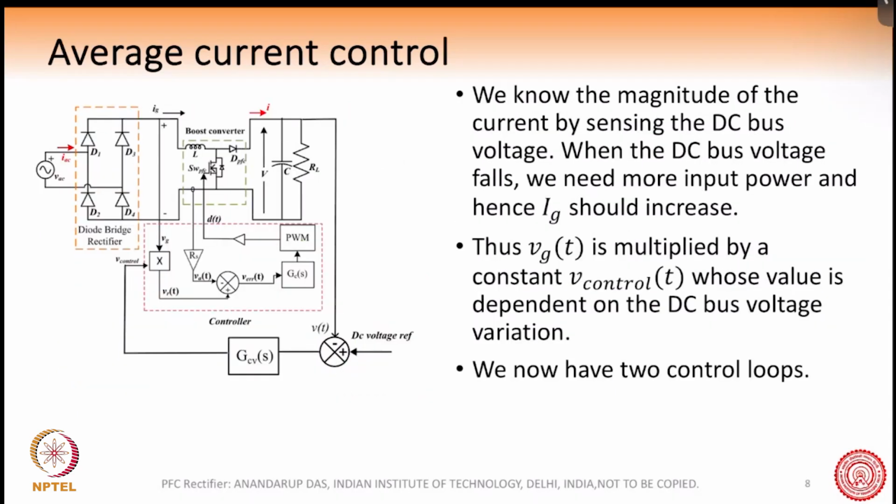How does it do that? Basically, remember we talked about this previously, in the three-phase voltage source converter. The DC link voltage has information about how much power is flowing, right? If you recall, if you take more power from the output, then the DC bus will fall.